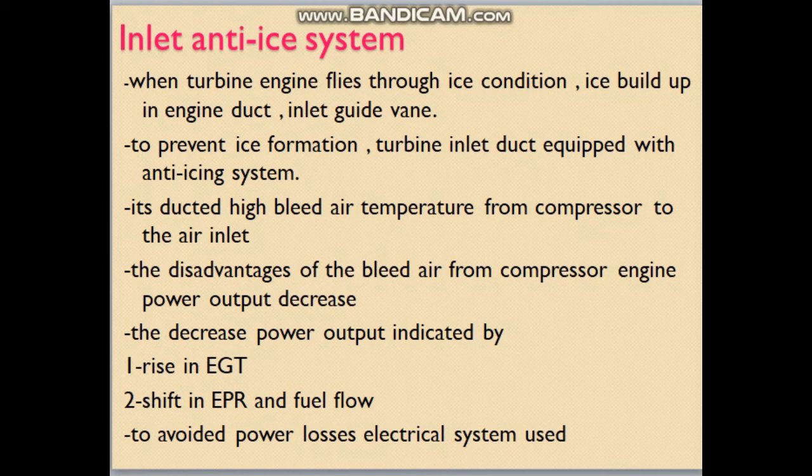With an electrical anti-ice system, electric heating elements are embedded in a rubber boot or placed behind a metal leading edge surrounding the intake, and this will help to prevent the ice.